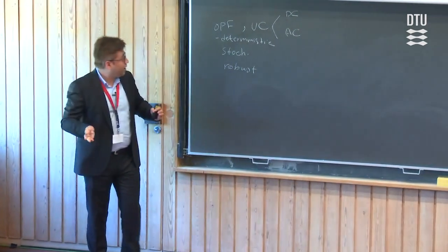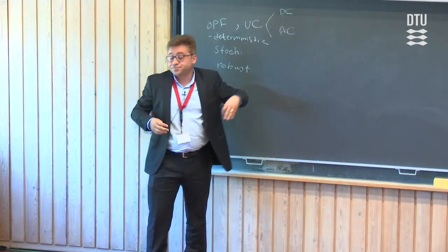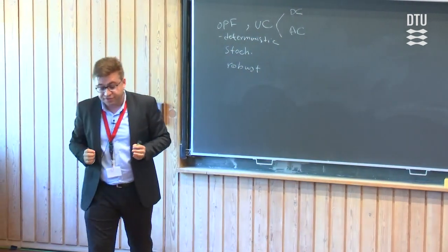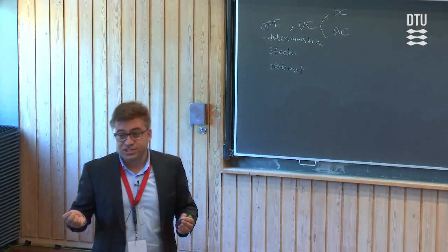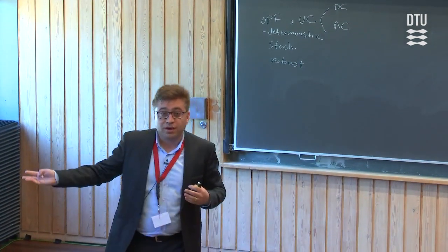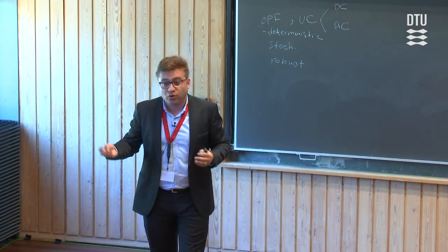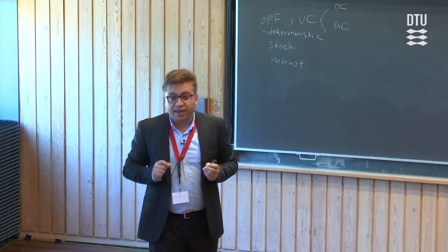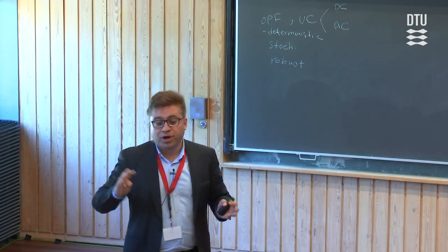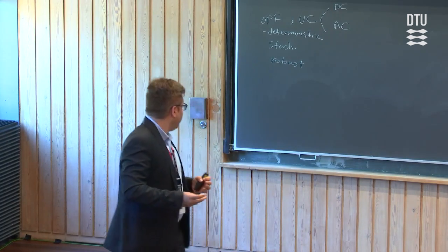And then Pascal again talked about the different versions of ACOPF, the different relaxations of the ACOPF, talking about second-order cone programming. How we can relax ACOPF and make it an SOCP problem in different versions, and then SDP.